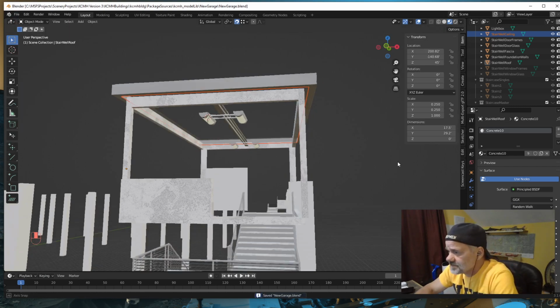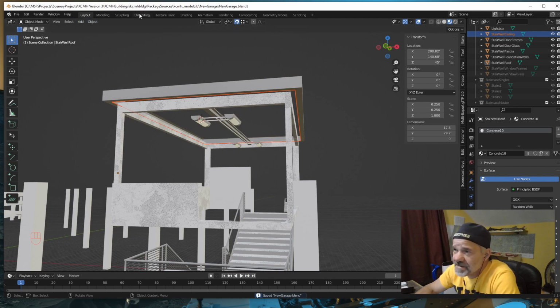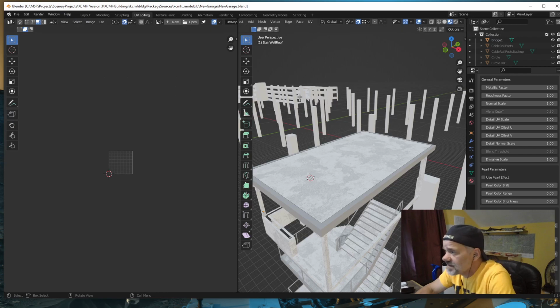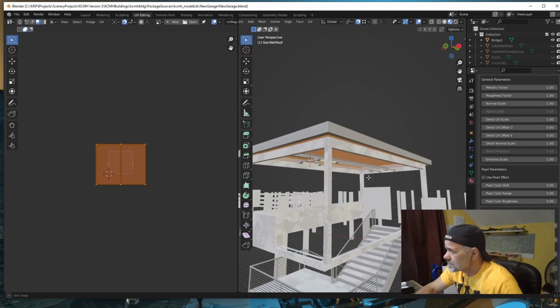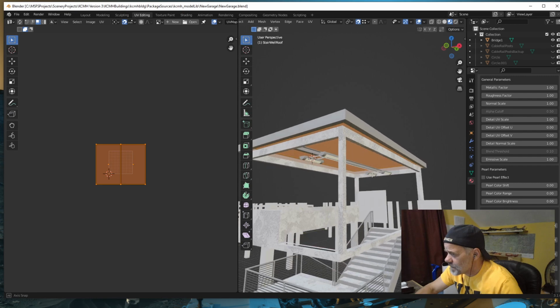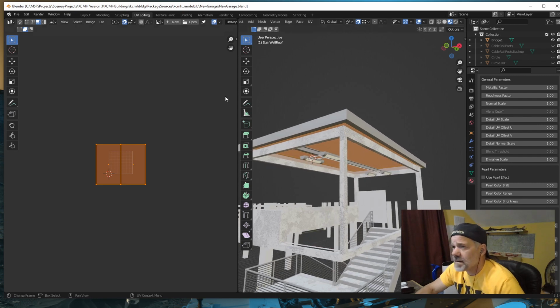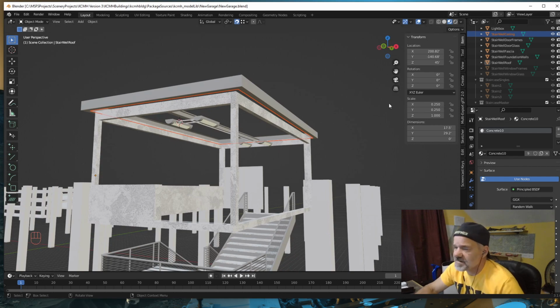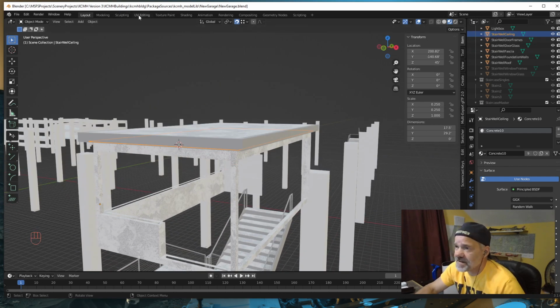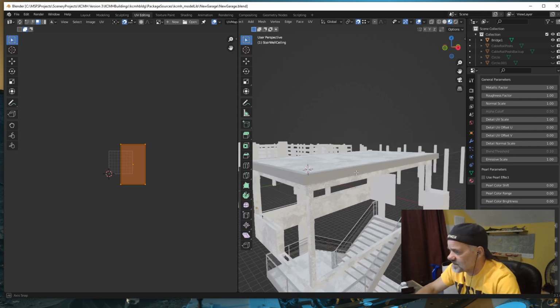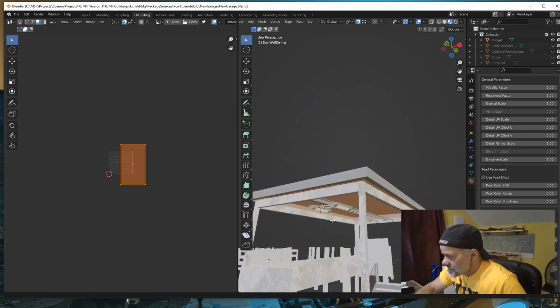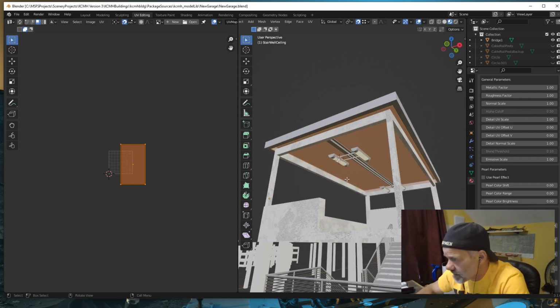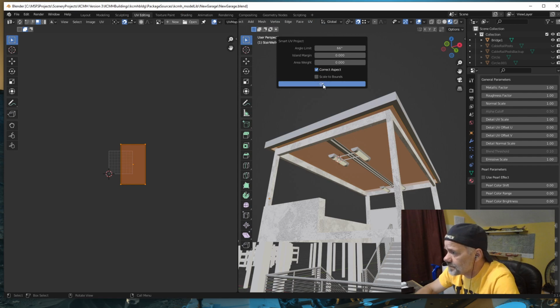Let's do a save. Now I'm going to go into UV editor. I don't need the concrete. Select all. Oh no. Oh no. What did I do? Should only have ceiling selected. Oh, I don't have ceiling selected. There we go. Now I have ceiling selected. Now I can go into UV. Hit A. Should not have it. Yeah, there we go. Alright, that was user error. IO error. Idiot operator. Alright, so with the ceiling face selected, UV, smart UV unwrap, and OK.